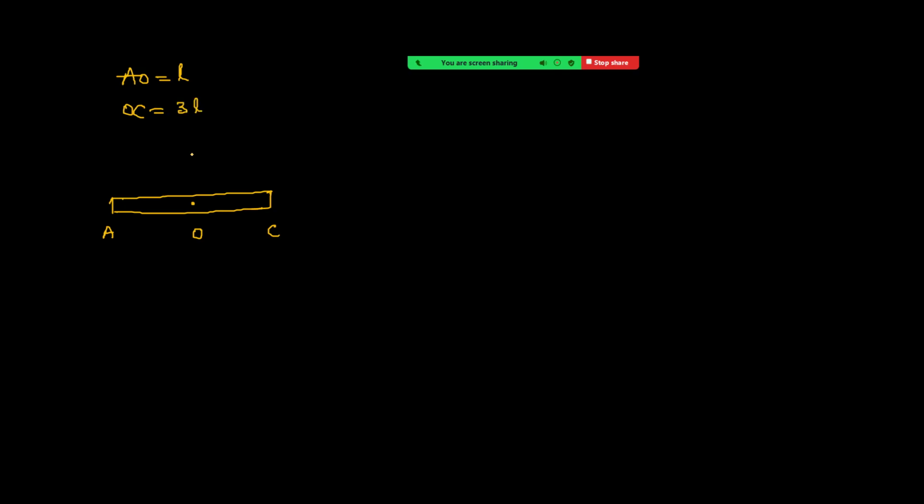Right? Again, the rotation is the same. The field is into the board, same as the previous problem. So then what happens is, you can see C becomes low potential, negative, because electrons will move towards C. In the same way, electrons will move towards C. So A and C are having negative potential and O will be at a high potential.